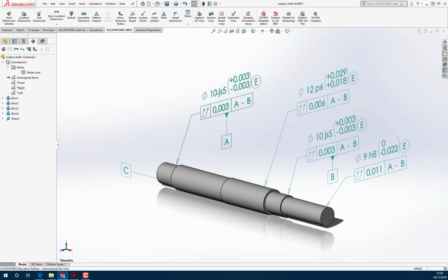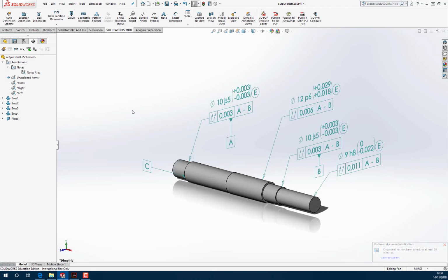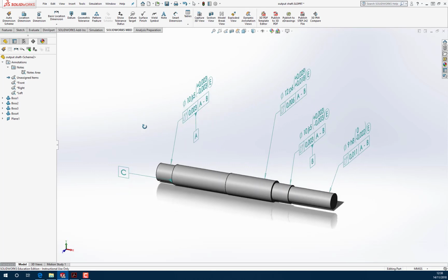It means that all the information about that surface is all in one place. It's the nominal size, the tolerance and the values of that tolerance, the fact that we're controlling it with the envelope requirement, and the run out and its own datum identifier, all of that is all in one place for that single feature. Okay, so that's quite useful.